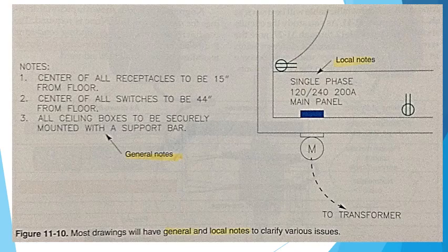Specifications. Specifications are documents that list the items of a schedule, the local code requirements not found in the NEC, and designations of those responsible for supplying the materials. Specifications, or specs, are included with the prints to clearly define what is to be done, how it is to be done, and who is responsible for doing it.